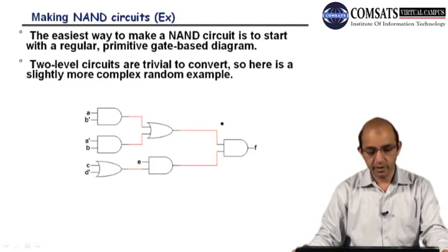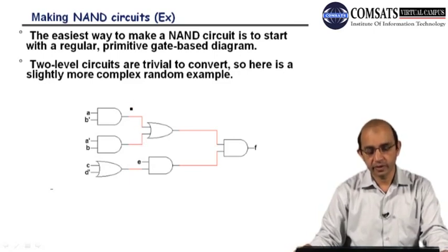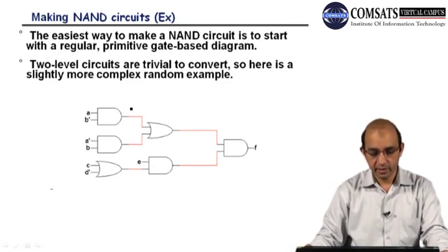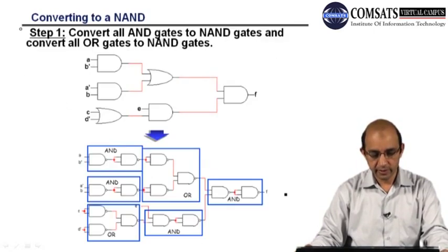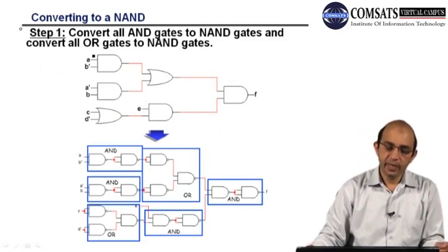And this is another example, a rather easier way. We have a circuit over here, and we want to implement the NAND-NAND logic, or we want to convert that circuitry so that all the logic is NAND, right? So you can see, we can straight away replace this AND with NAND.